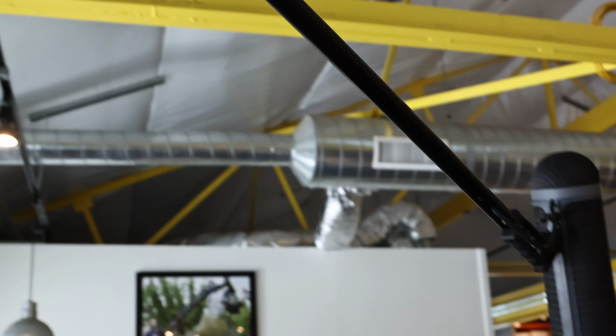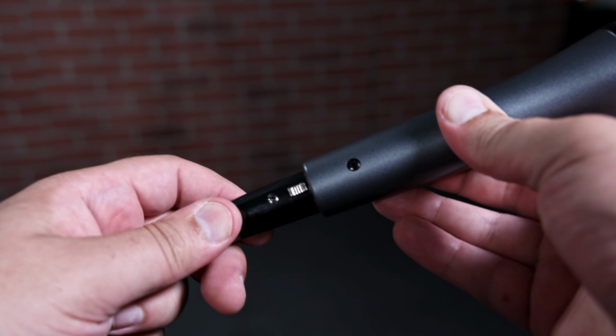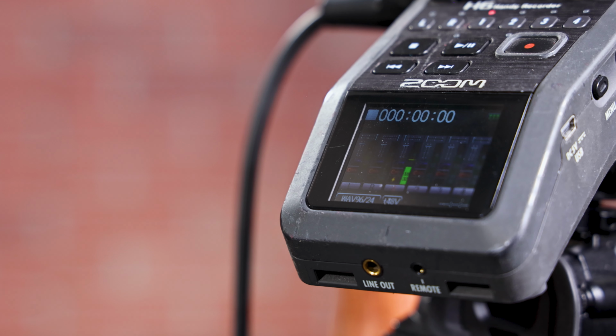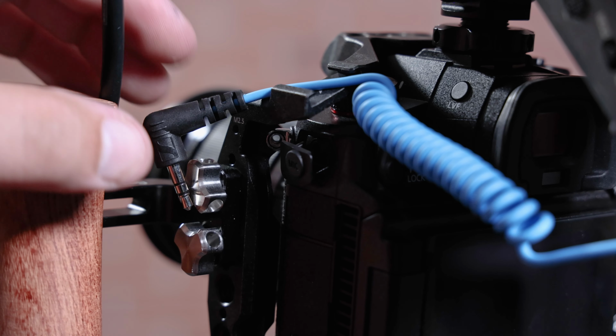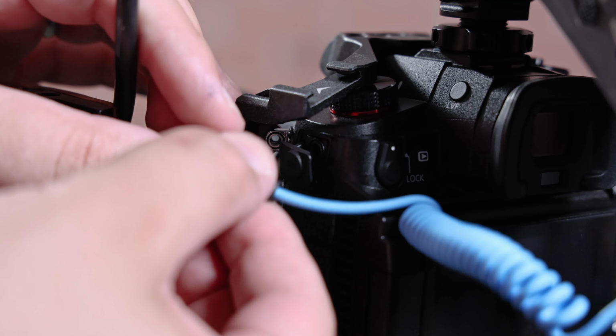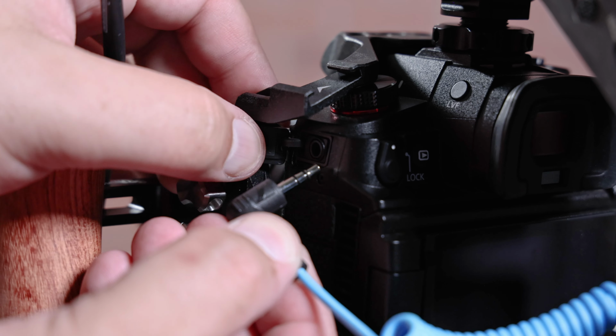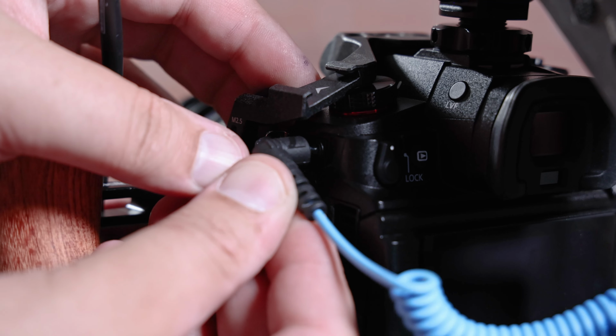For example, let's look at the same signal flow in the previously mentioned situation. In this case, following your signal flow allows you to identify an issue, but there's a signal at the sound source. The microphone has its cable installed, and there's a signal level on the preamp. With this information and following the signal flow, you can pinpoint the problem. The cable between the camera and preamp isn't plugged in. Once installed, the signal goes all the way from the microphone to the camera.